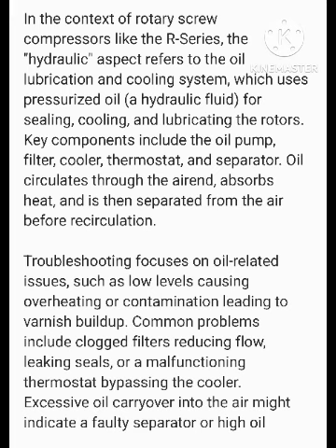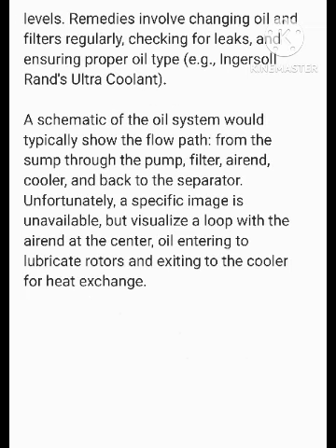Troubleshooting focuses on oil-related issues, such as low levels causing overheating or contamination leading to varnish buildup. Common problems include clogged filters reducing flow, leaking seals, or a malfunctioning thermostat bypassing the cooler. Excessive oil carryover into the air might indicate a faulty separator or high oil levels. Remedies involve changing oil and filters regularly, checking for leaks, and ensuring proper oil type, e.g., Ingersoll Rand's Ultra Coolant.